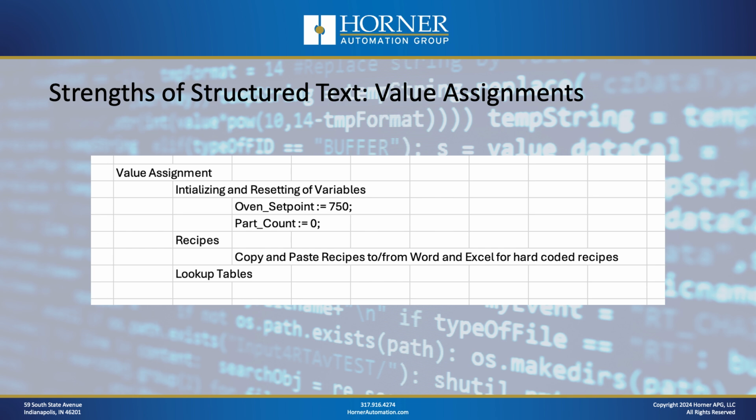And also the ability to build lookup tables probably is pretty powerful there. Very powerful. And that's with arrays, which were really the first thing in IEC. You now have that in advanced ladder with variables, but you did not have true arrays in the original advanced ladder. And the fact now that I can do looping functions and go through these tables or arrays. Nice.